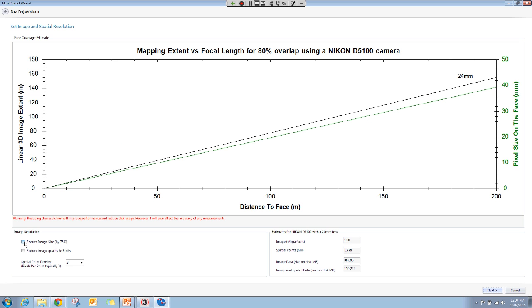As you try and process images that size through software, it takes longer to process. It slows everything down. So we needed to add in a method to reduce the image size without compromising the quality of the point cloud or of the wireframe, so you don't compromise the quality of your structural mapping.